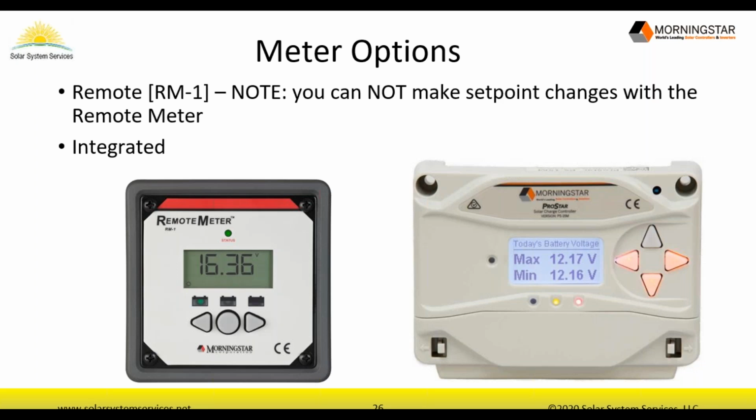Also, we'll get into more detail, but the neat thing is you can make set point changes via the display. So I think having this new meter option is really helpful and flexible because it allows you to make changes right there. You don't have to plug in with the computer. The one negative is if you have a customer you do not want to make changes or settings to it, you probably don't want that feature then.